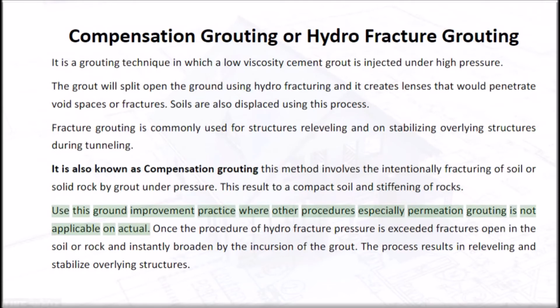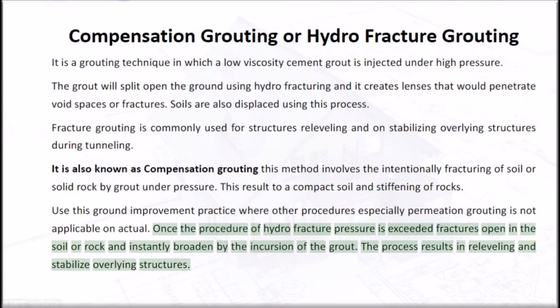Use this ground improvement practice where other procedures, especially permeation grouting, are not applicable. Once the hydrofracture pressure is exceeded, fractures open in the soil or rock and instantly broaden by the incursion of the grout. The process results in releveling and stabilizing overlying structures.